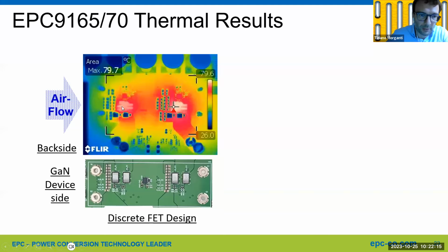We can also measure the temperature of the power stage with special very small optical temperature probes, but this is the easiest way to assess the results, and the temperature underneath the PCB is pretty close to the die temperature.